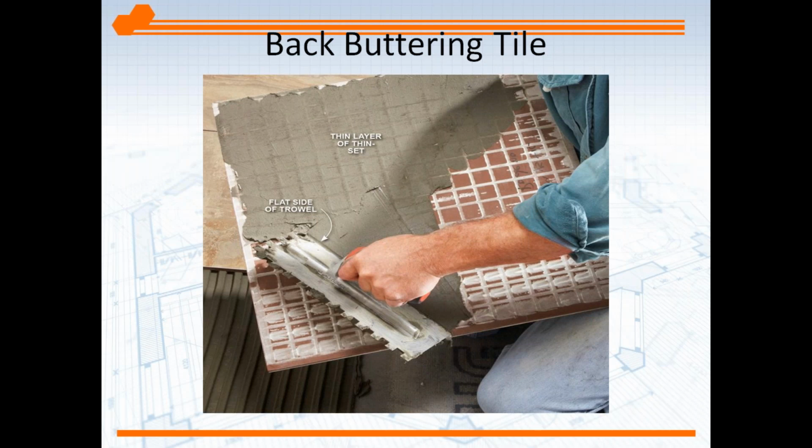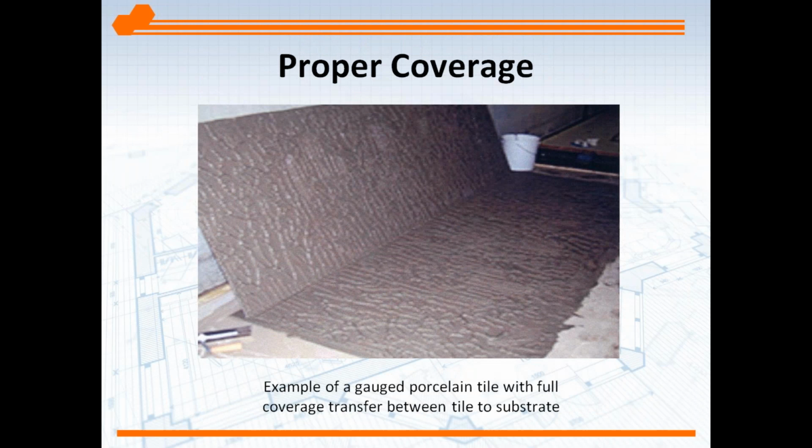Of course, the tile installers are supposed to, every once in a while, audit themselves. Pull up a tile, take a look, make sure you're getting the proper coverage. But this is the way to do it. Now, this is incredibly good coverage, right? This is 100% coverage. And we'd love to see this on all installations.